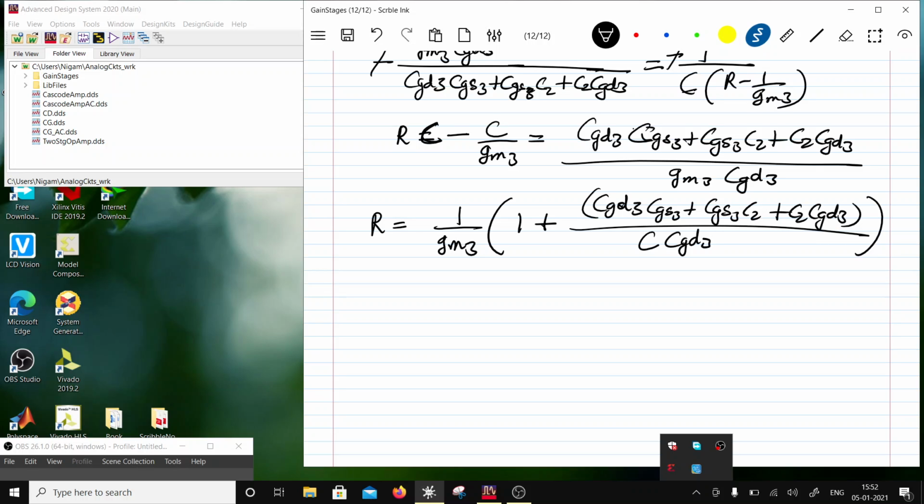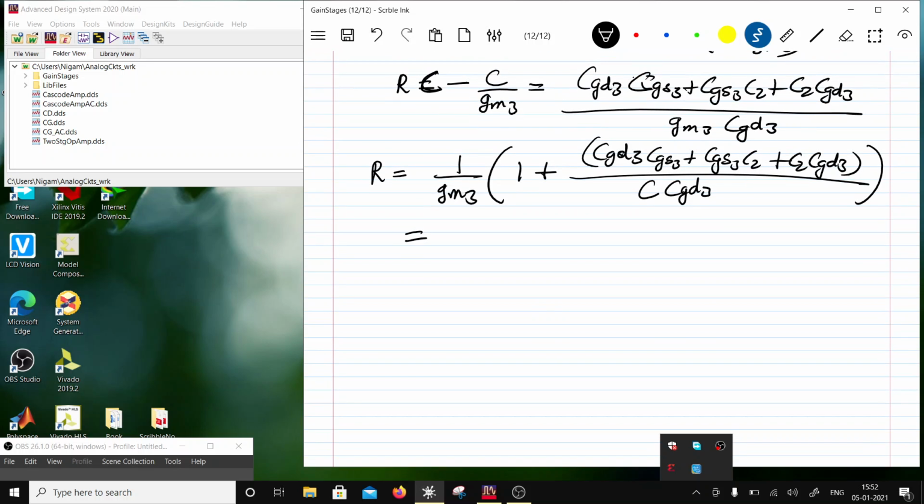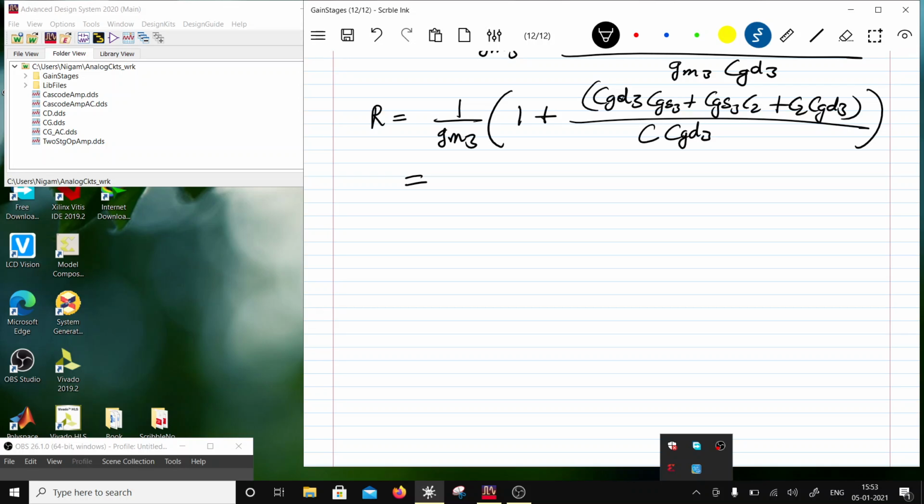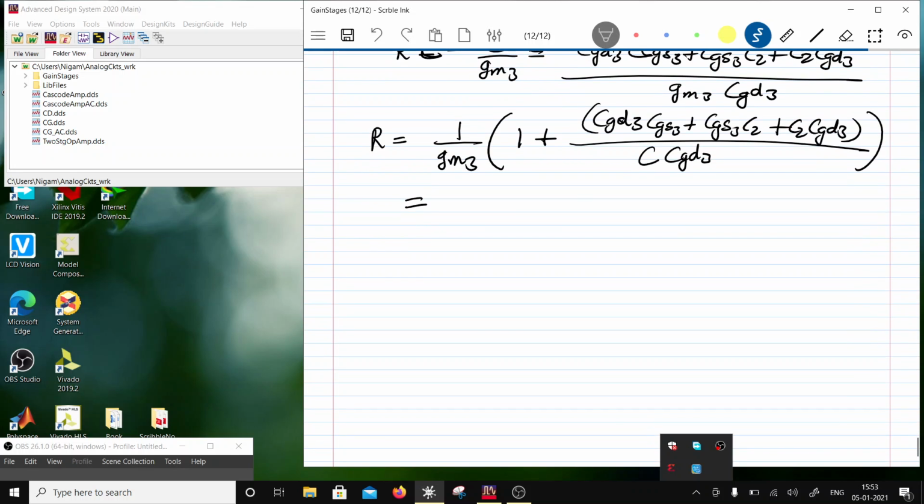So this is going to be cancelling the second pole. So once you cancel the second pole, what's going to happen? If you introduce a pole and a 0, then the phase roll off minus 90 plus 90 is cancelled, right? But you still have got 40 dB per decade of roll off, right? Because one would be 20 because of the 0, other would be 20 because of the second pole. So the total roll off will be minus 60 dB per decade, right? So when you cancel the second pole with a 0, this will happen when R is equal to this number.